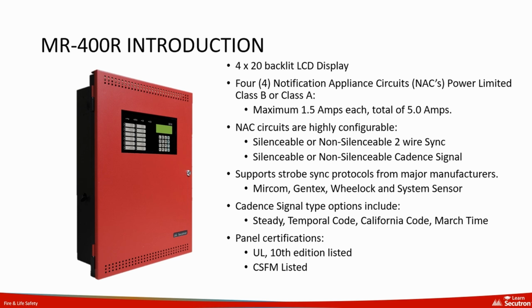The MR-400R features a 4x20 backlit LCD display, equipped with 4 notification appliance circuits, or NACs, each capable of providing a power-limited output suitable for either Class B or Class A operation, with a maximum load of 1.5 amps per circuit and a combined total capacity of 5 amps.